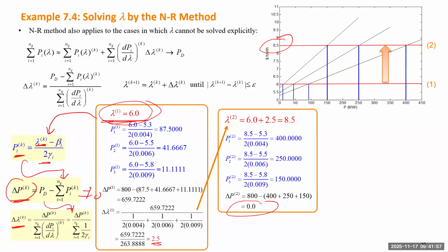Okay, so you have 2 approaches to solve economic dispatch. First, you can use those formulas, and second, you give it some initial guess and just iterate, and after some iterations, it will reach a final solution. So for the economic dispatch problem without inequality constraints, which means all the generators have no limit, both approaches are fine. But when we move to the new problem with generator limits, this approach is better, because it can iterate.